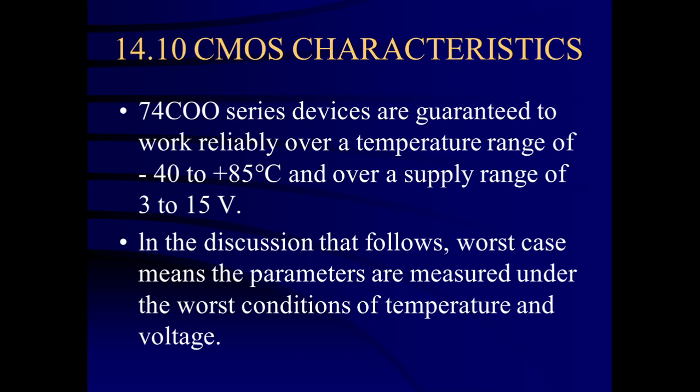This temperature range is -40 degrees Celsius to +85 degrees Celsius in case of the CMOS. -40 degrees Celsius is extremely low, like in Canada or Antarctica, and +85 degrees near the equator, etc. This IC can work reliably there, so no problem. You can mostly utilize this commercial applications IC only. That is more than enough for you.